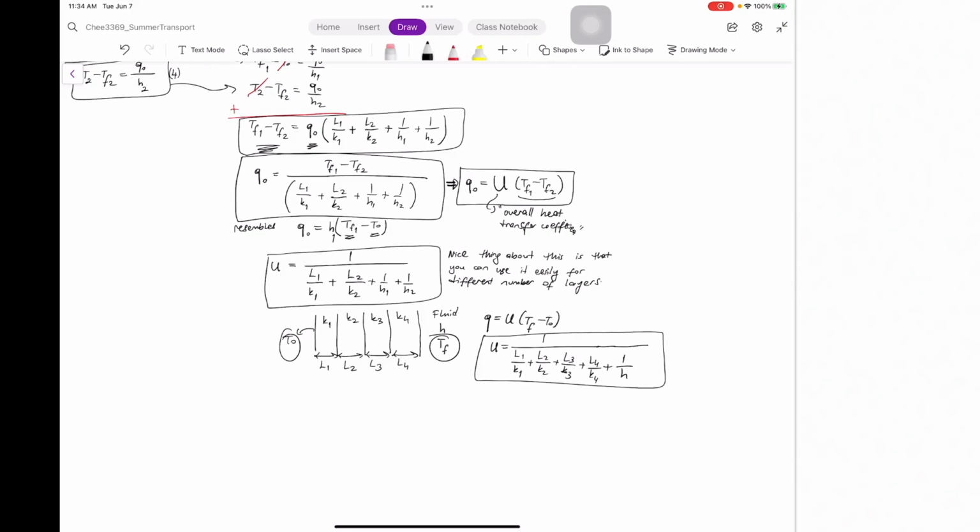And these equations also look like the equations you learn in physics classes, I guess. It's Ohm's law, right? The additivity of the resistances. Well, basically, it's the same thing. You're adding the resistances here. In this case, we have the flux is equal to the difference in the temperature delta T, which is the driving force for the heat to move from one place to another, divided by resistances.